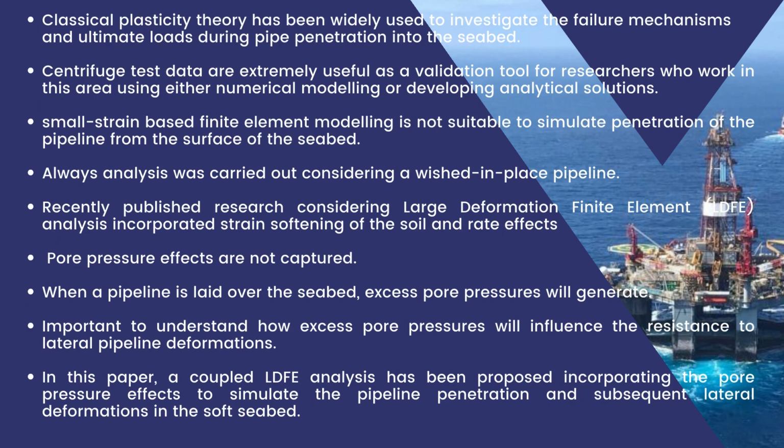So, classical plasticity theory has been widely used to investigate the failure mechanisms and ultimate loads during pipe penetration into the seabed. Centrifuge test data developed are widely used to validate numerical models and analytical solutions. Normally, small strain based finite element modeling is not suitable to simulate the pipeline penetration because of the large soil deformations around pipelines during seabed penetration.